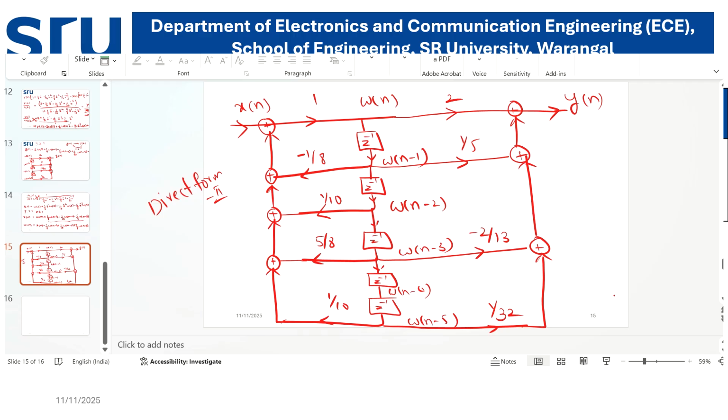Now here for w of n minus 2, we don't have a connection. Similarly for w of n minus 4 also we don't have a connection. Suppose in the given expression, if these terms are also available, then you have to use one more adder for each term. And coming back, the number of adders required is 5 plus 5, that is 10. And the number of memory locations, the formula is maximum of m comma n. The maximum of 5 comma 5 is 5. Alright? So 1, 2, 3, 4 and 5.